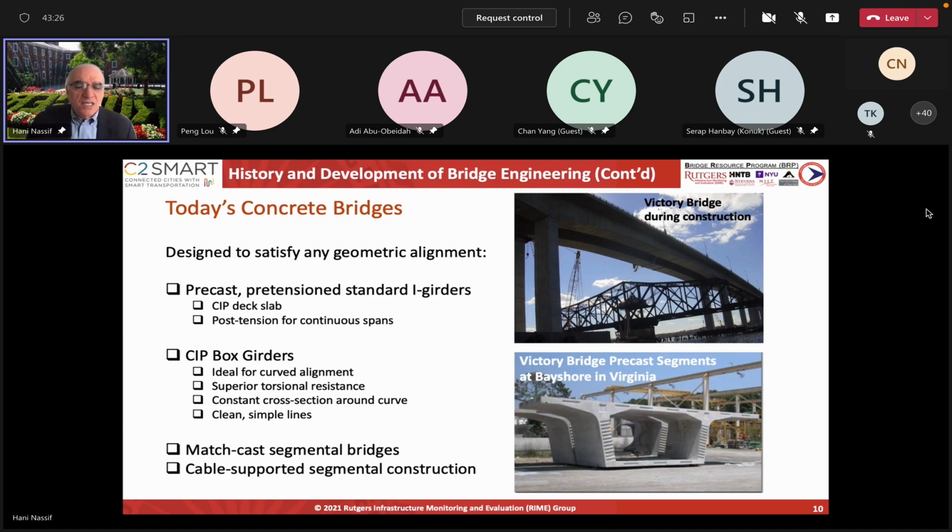But we are proposing a combination of bonded steel and unbonded FRP tendons. And by that combination, we are retaining the ductility and the enhanced cracking performance that you would get. And I think with my colleague Adi Ubaida, we published a couple of papers on this topic.